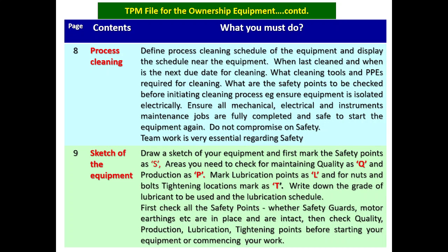and what are the safety points to be checked first before the cleaning process. The topmost point is to ensure the equipment is isolated electrically. Once the cleaning work is over, ensure all mechanical, electrical and instrument maintenance jobs are also completed and the equipment is safe to start again. Do not compromise on safety. Teamwork is very essential regarding safety.